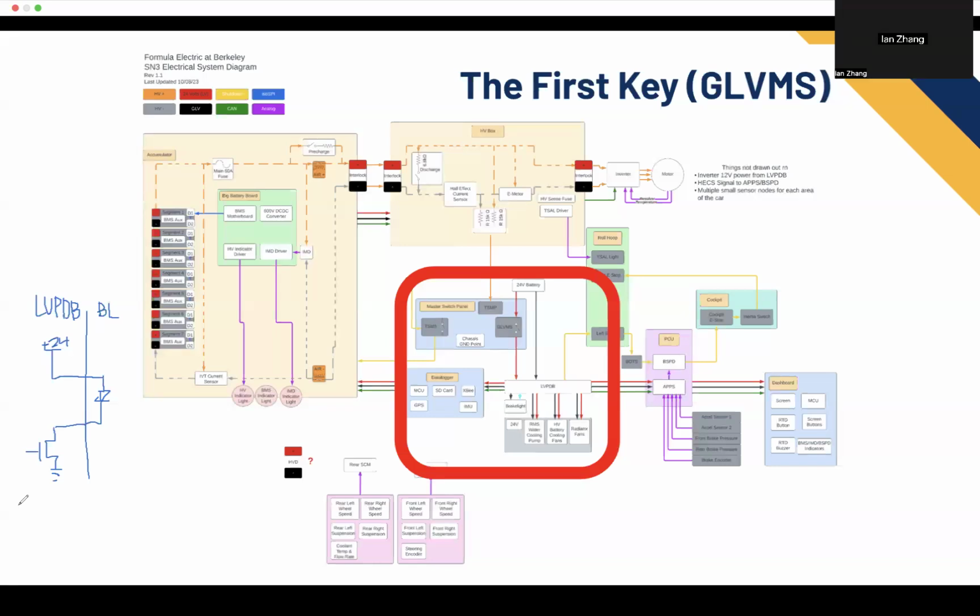And then biasing those LEDs, because there's one component that's missing here. When it comes in, you put a resistor there, and then it goes through the LED so that the proper voltage drop is across the LED. So basically, how do you bias that?